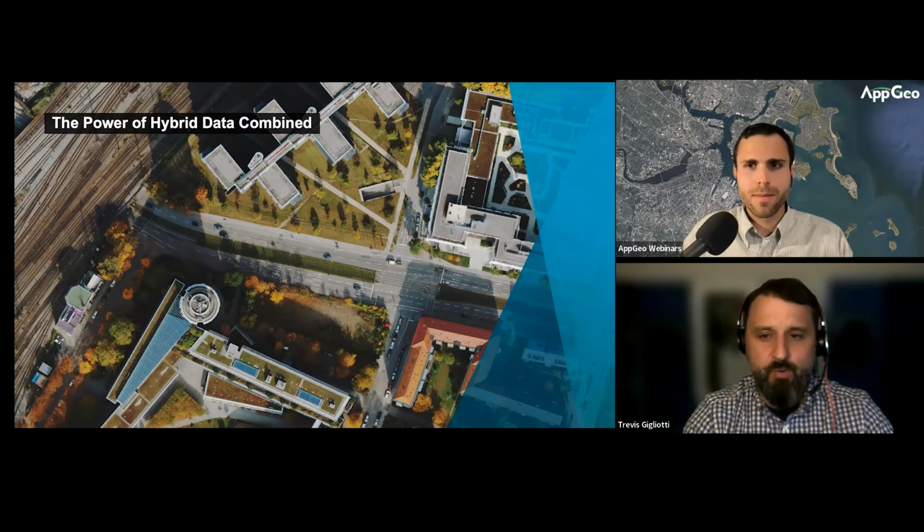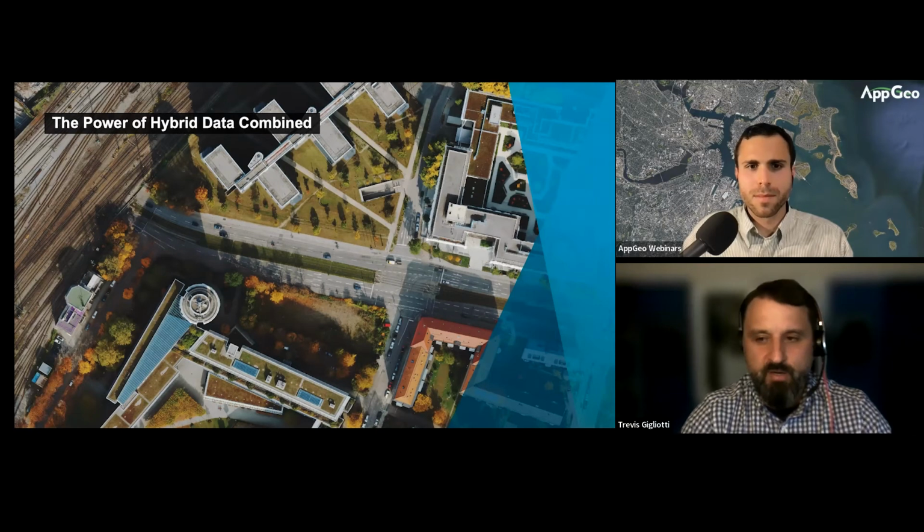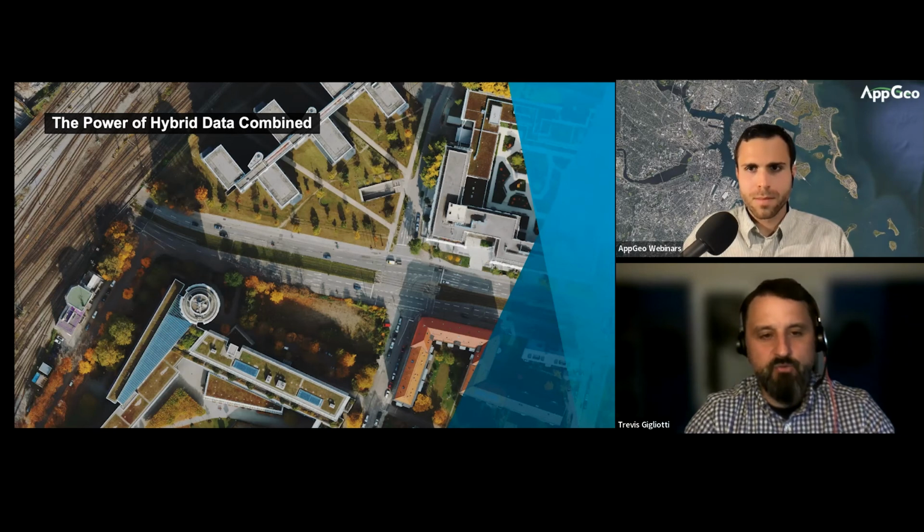Yeah, so the first data set that we're looking at here, Aaron, is our True Ortho product. In addition to our standard ortho rectified imagery, which comes out of the data collection, we offer a True Ortho rectified product as well, which is rectified using the LiDAR DSM as opposed to a DEM. And so we're able to remove the appearance of building lean in the imagery, for those that aren't familiar. Each pixel is represented as viewed directly from above in its true orthographic position. The important thing to note here is this is a bona fide 2D map with high resolution imagery as its context. The normal GSD for the imagery that we collect is 5 centimeters, so it's extremely high resolution.